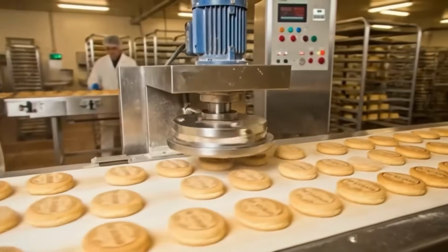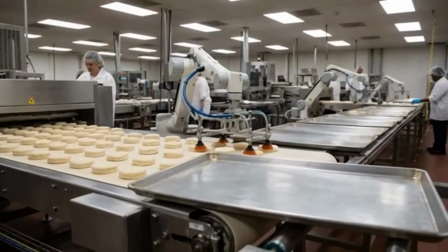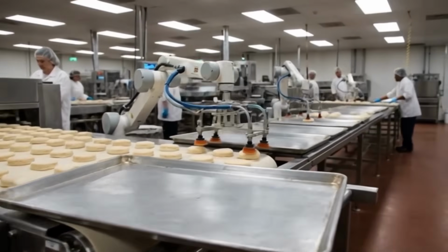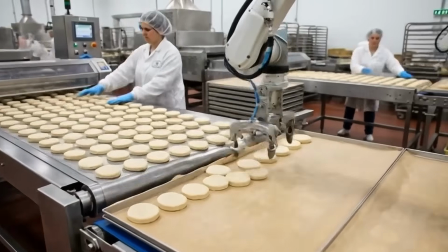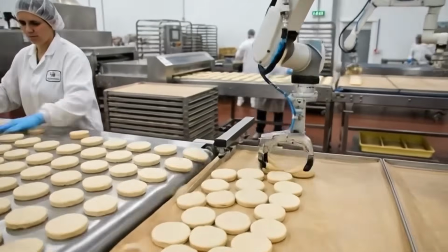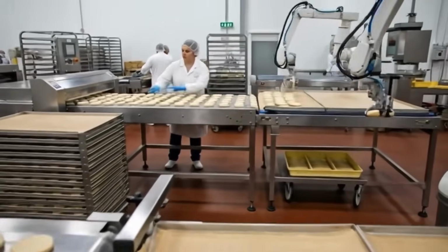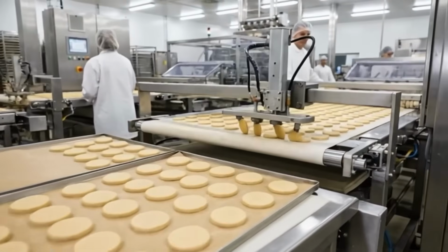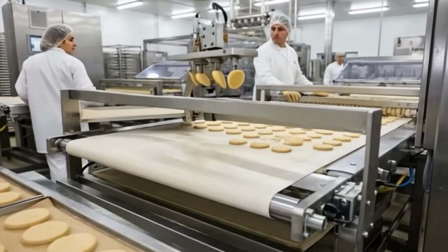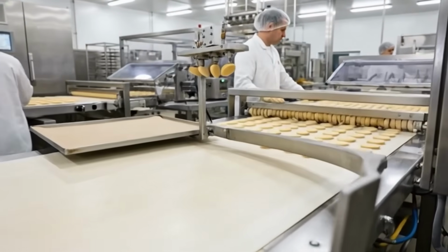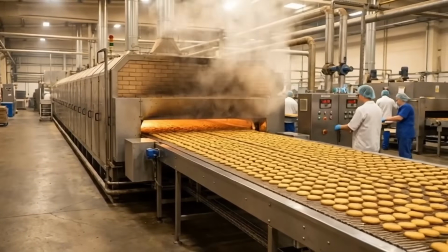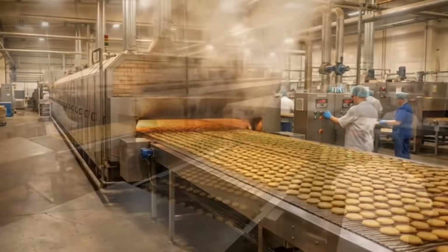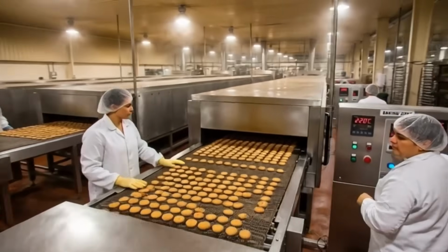After mixing, the dough often enters a rest stage. Rest allows moisture to distribute through flour particles. Rest also lets the dough relax and reduces elastic snapback. Reduced snapback is important for precise cutting and consistent size. Rest temperature is controlled because warm rest softens fat and changes dough stiffness. The dough then moves to forming, which can be sheeting, extrusion, or molding.